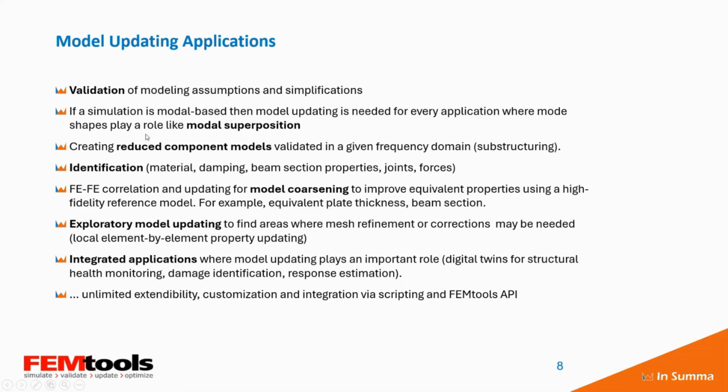It can serve different applications, like validation of modeling assumptions. As we are doing this in the modal domain, it's a very important domain because it's the industrial approach to frequency and time domain response analysis by using the modal superposition technique.